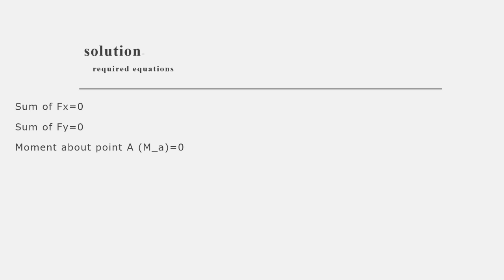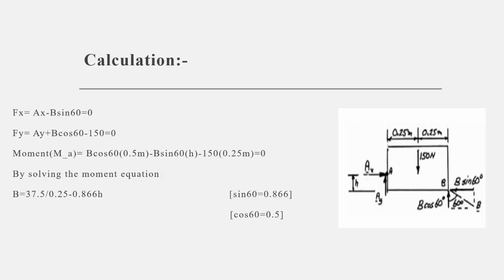Okay, now let's get into solving the equations. While solving ΣFx, we take the components in the x axis. We have Ax and B sin 60. What is going to the right side is always positive, and to the left side it is negative. B sin 60 is going towards the left, so ΣFx = Ax − B sin 60.